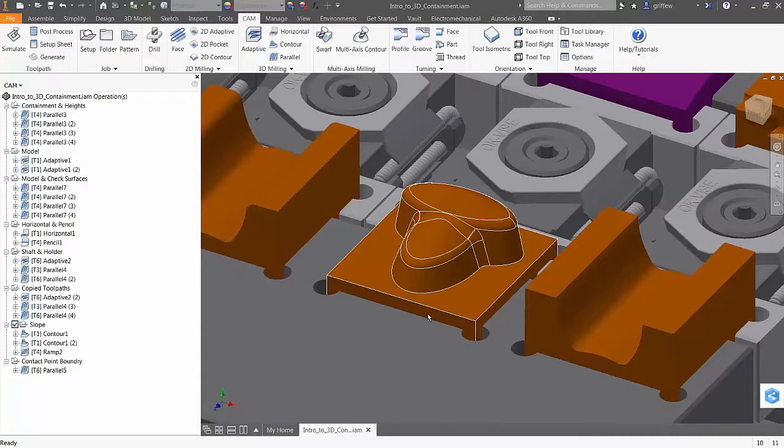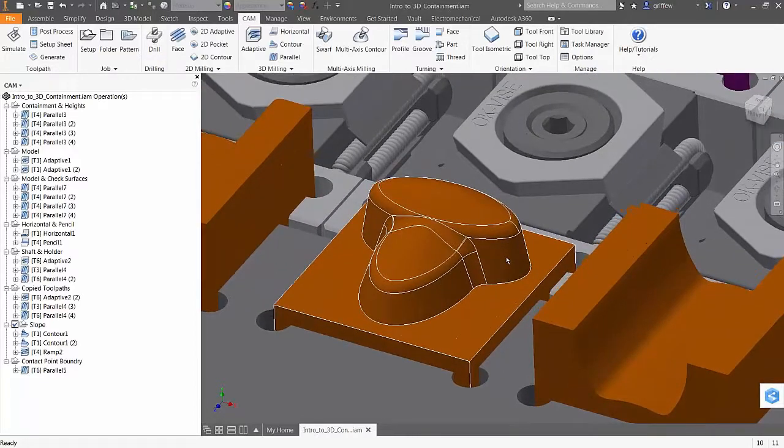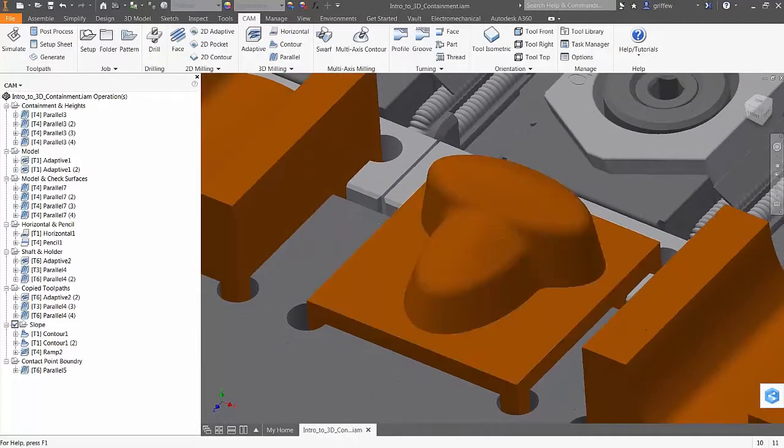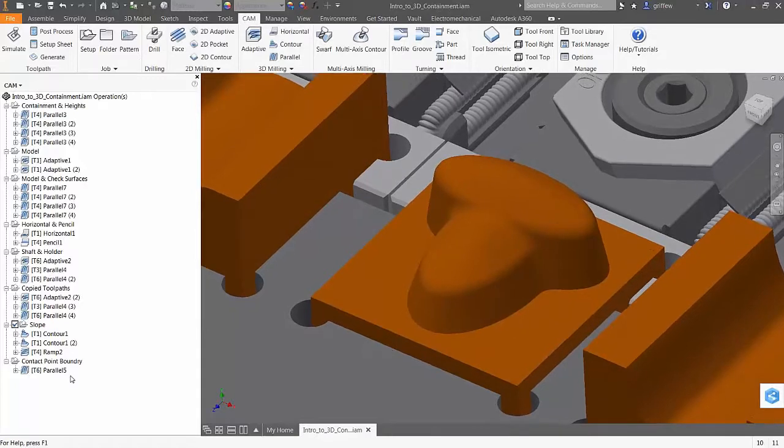But that's the way I think of it. That's really my understanding of how it works. I could be wrong about why you're getting more code. There's a lot of variables in there, the way your tolerances are, if you have smoothing set up, really how your machine interprets a lot of that motion, your post. So there's a lot of variables as to why you would get more code, but as far as the differences between the toolpaths, those are the things that I see.